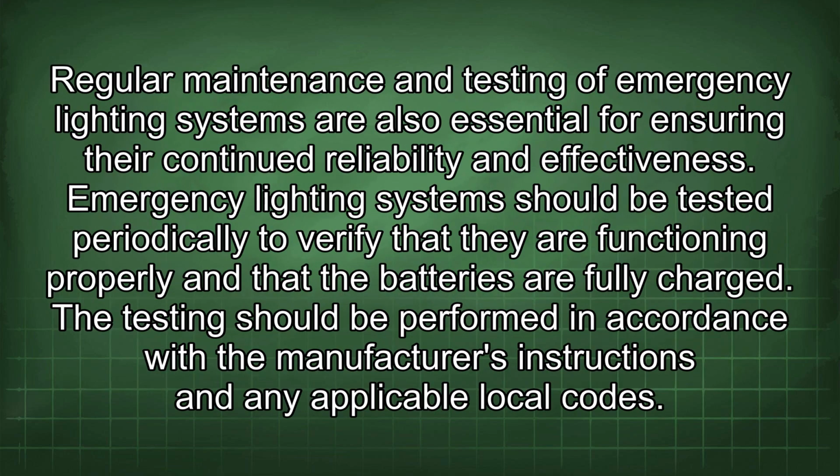Regular maintenance and testing of emergency lighting systems are also essential for ensuring their continued reliability and effectiveness. Emergency lighting systems should be tested periodically to verify that they are functioning properly and that the batteries are fully charged. Testing should be performed in accordance with the manufacturer's instructions and any applicable local codes.